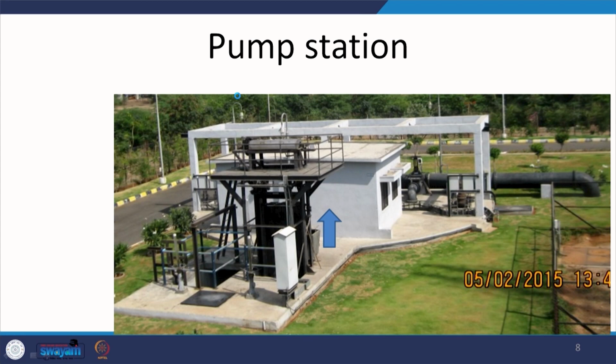So, pumping station, let us see what we have. So, this is the pumping station, right. The underground sewer is coming in, and these are the screens that we see, coarse screens typically before the pumping station, and then the sump well where the wastewater is being collected. I think you saw this in the video also, for the IIT Roorkee sewage treatment plant.